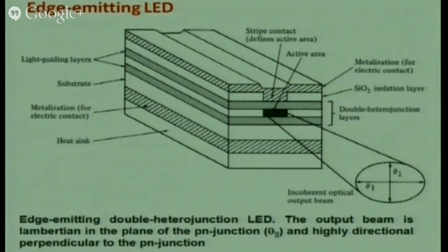And these are insulator layers. This is all insulator. That means my electron holes will not transport to this region. They are all available within this. So I am confining my recombination process within the active region to a very narrow region. So the maximum light output I can get from that region. Clear?